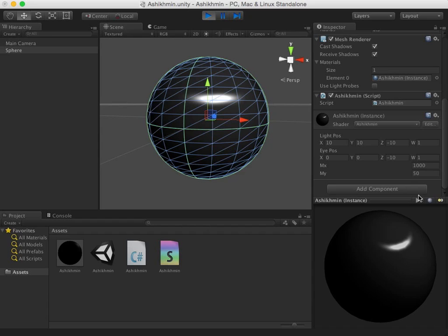Now, we can play with those figures if we wish. So I guess I could push that up to 10,000, and we end up with this strongly anisotropic effect, which approximates that it's strongly brushed along that direction, but not up and down. So the light is guided, so to speak, I think that would be an appropriate term, along those lines and not reflected much across the axis.